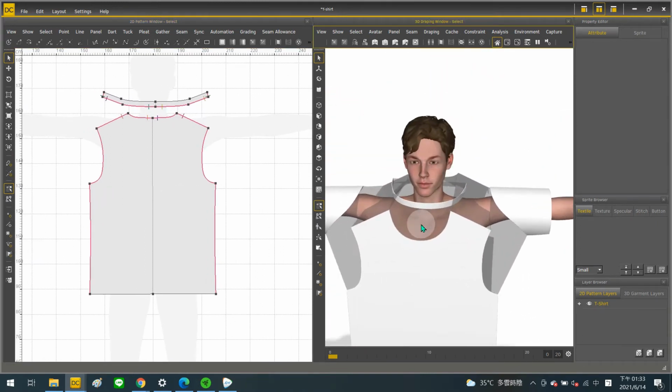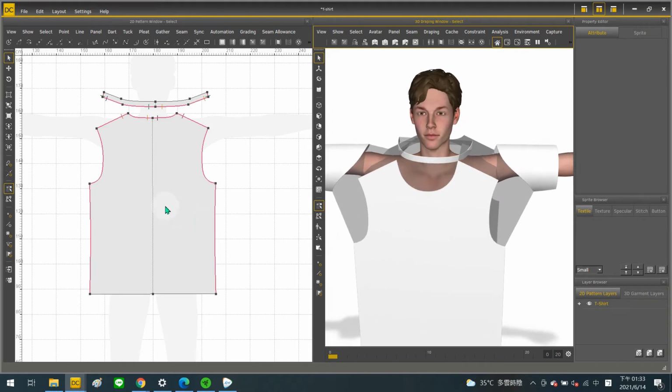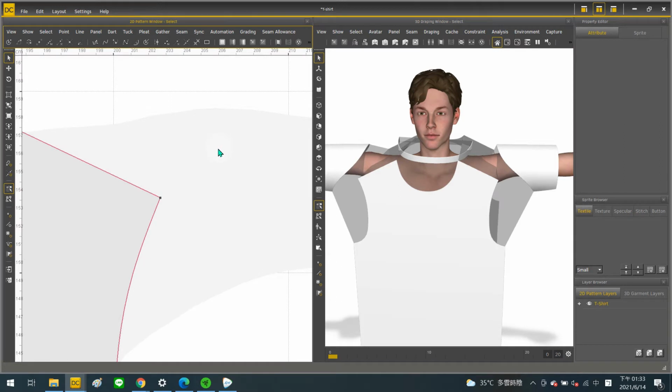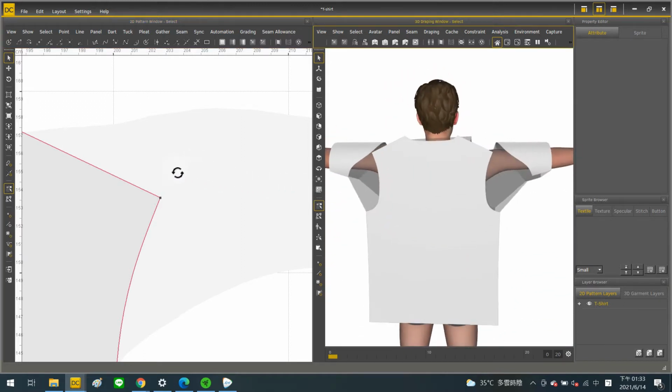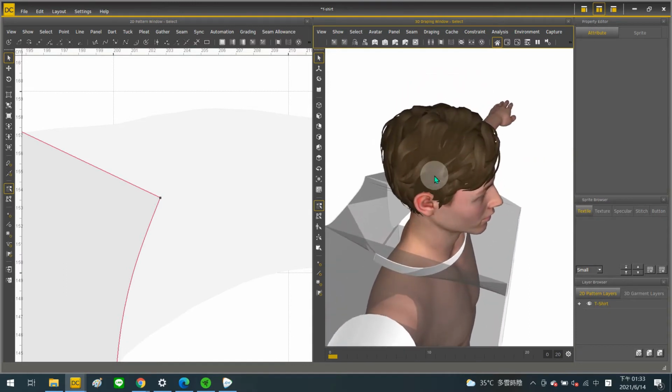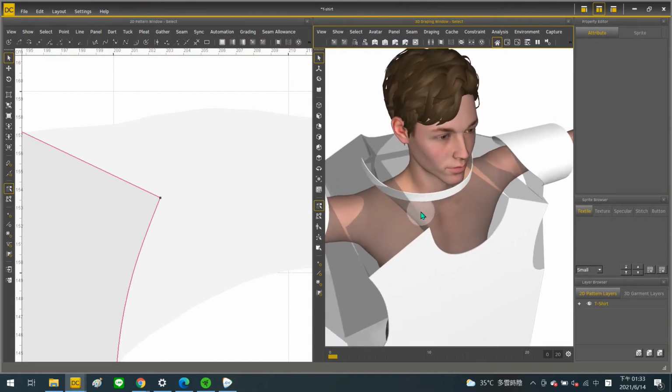In the 2D window, if you use right click to do box selection, it will bring you to the view to fit the box you just made, which is the way you can zoom in very quickly to the target. In the 3D window, pressing the right key and holding it, you will be able to turn your view angle.